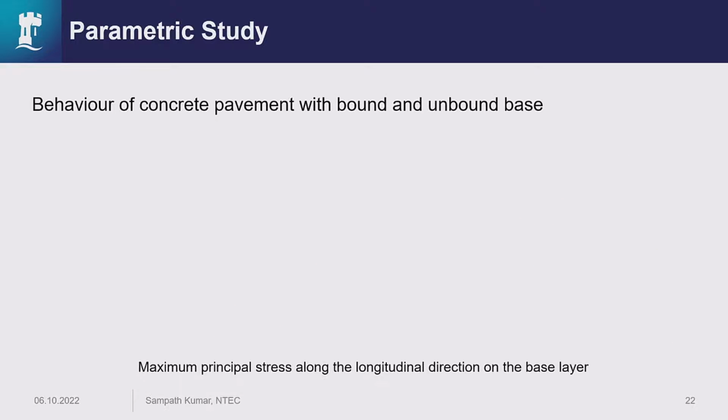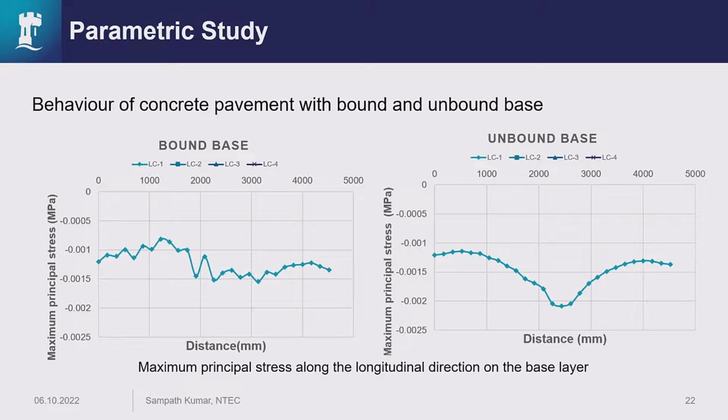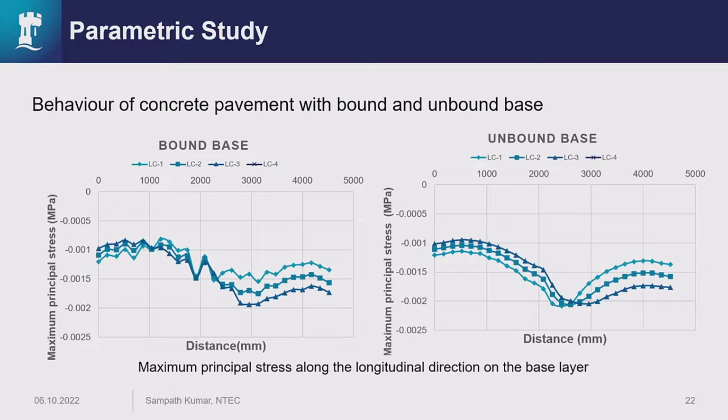And we have also studied what happens to the concrete pavement with a bound base and without a bound base for different load cases. I'm going to go fast here, but you can see clearly this is a linear relationship, where you have more stresses in the unbound case, and less stresses if there is a bound base.